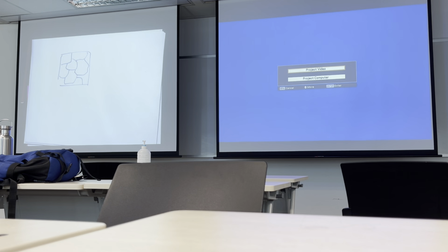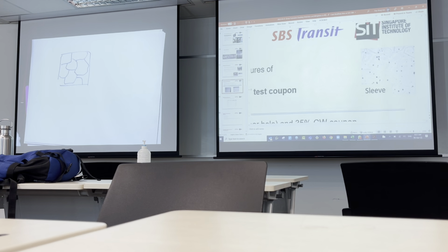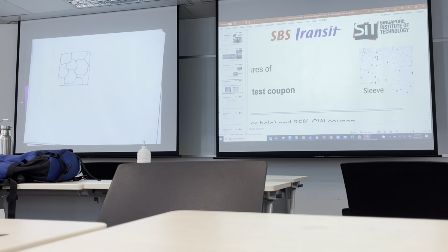So maybe this example, this is a work that they pay us quite a bit of money to do. So this one, you see all the grains, right? How do we actually see the grains? The grain boundaries. Actually, what we do is we take a sample, we go to the lab, we polish and grind until it's mirror finish. We polish, it looks like a mirror.